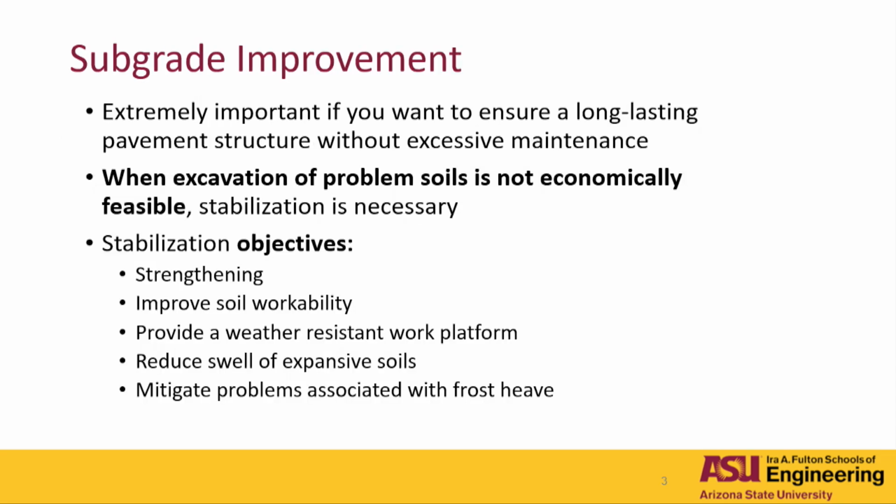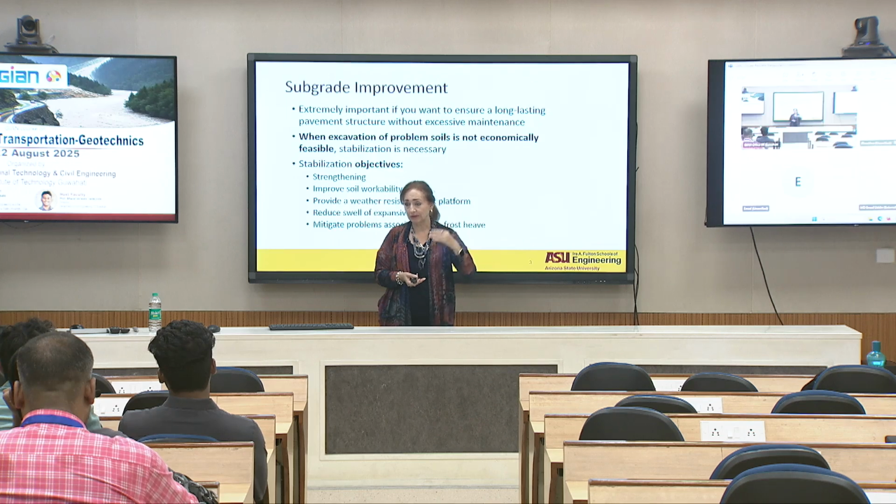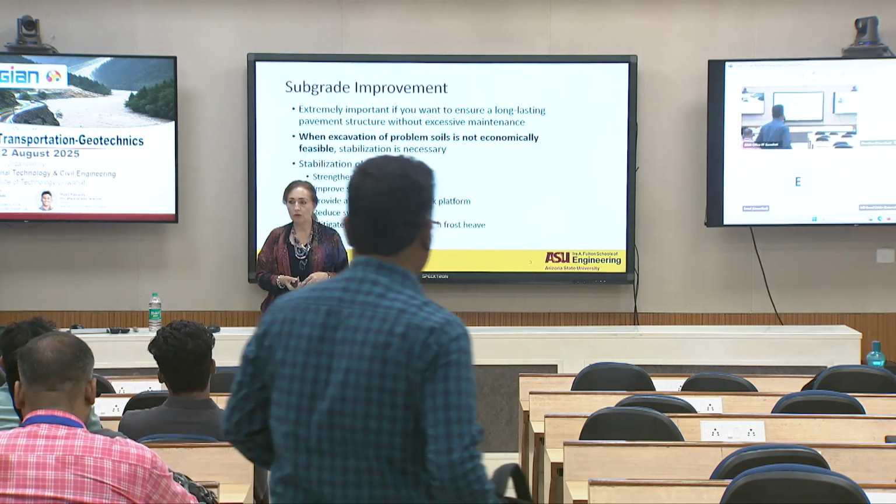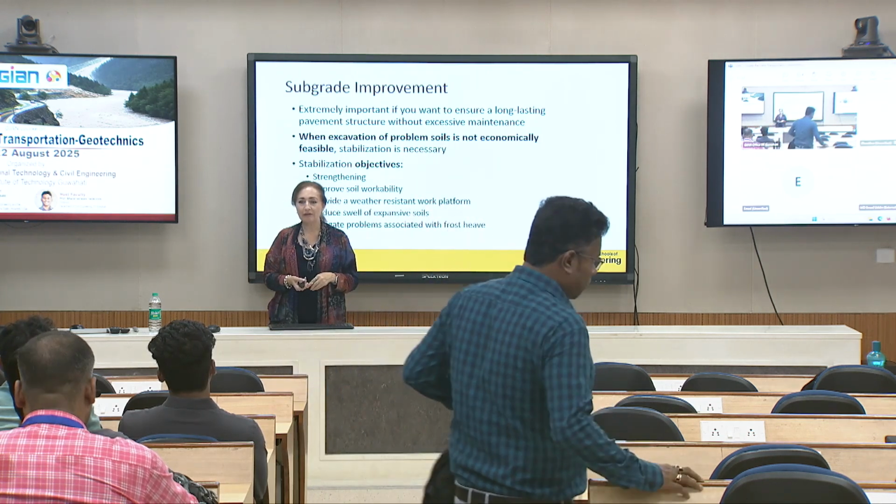Okay, so why subgrade improvement? Well, I put in here that it is extremely important if you want to ensure a long-lasting pavement structure without excessive maintenance and movement, right? Usually we avoid soils that are problematic. We just excavate, right?